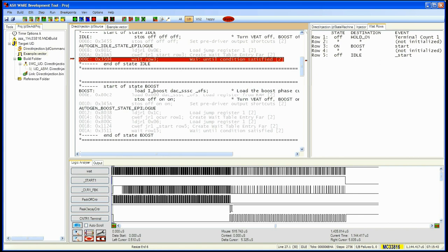This is a brief period between the peak and hold portions of the injection cycle when the injection current is allowed to decay from the higher peak level down to the lower hold level. During the latter half of the injection cycle, counter 1 is active. Note that this is the name of the counter given in the documentation. Unlike the other 2 counters, no more easily understood name has been assigned to this signal in the Ashware simulator.